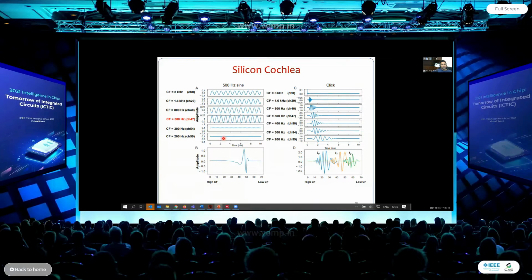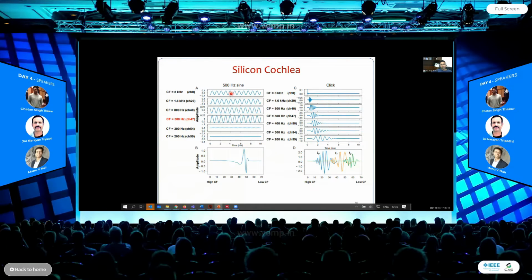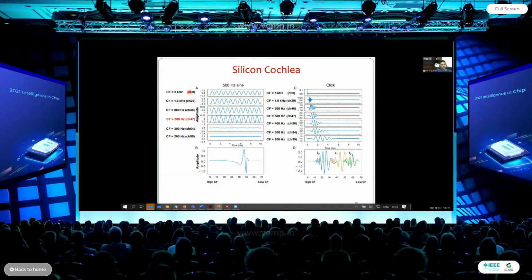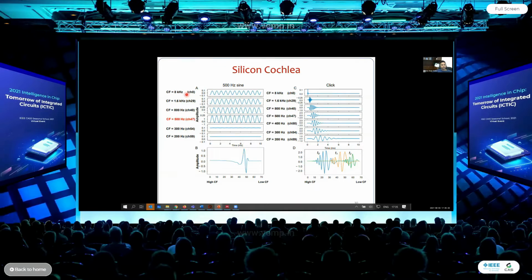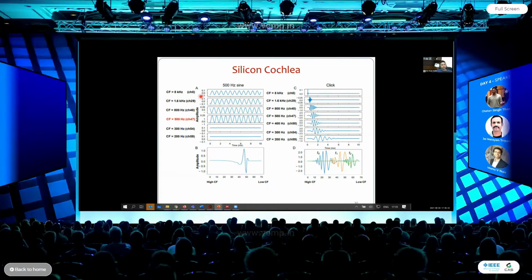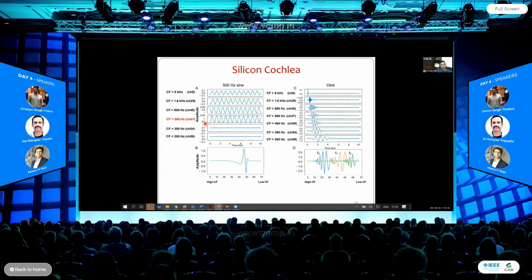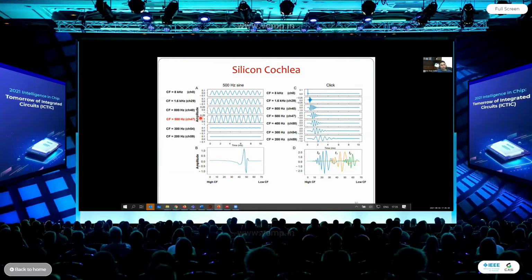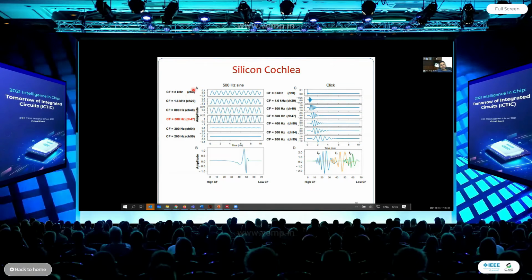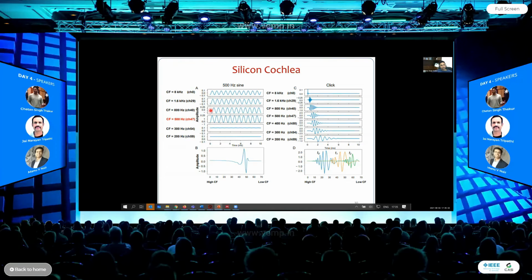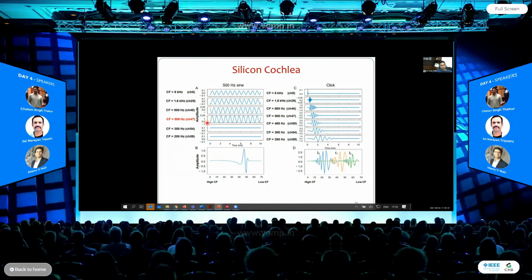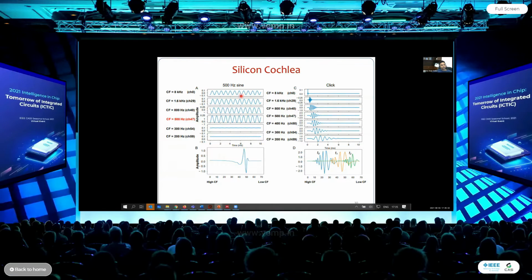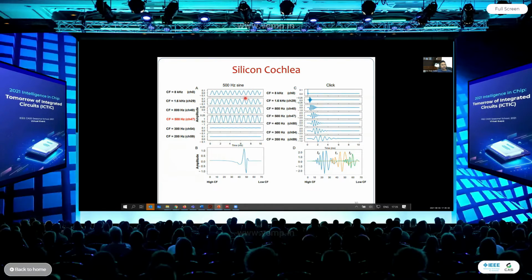These are some of the time domain results of the same cochlea. Here you can see this is channel number 0, which is the highest channel, 8 kilohertz, because in this particular configuration we have a filter range from 50 hertz to 8 kilohertz. The highest frequency is called channel 0. And you can see the gain at 500 hertz is highest, and then the rest is decreasing. At the lower channels, you won't see anything if you play the 500 hertz sinusoidal tone.